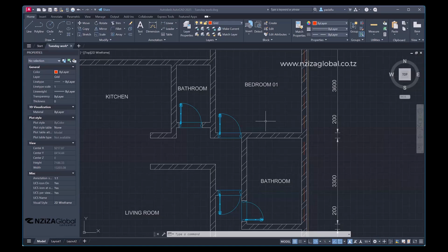It shows where beams are passing and the location of columns in our floor plans. So we need to create this. In AutoCAD, you have an automatic way to create this kind of grid without just using text, typing a number, making a circle and drawing the lines. We just have to have one thing as a grid. So that's what we were trying to create there.